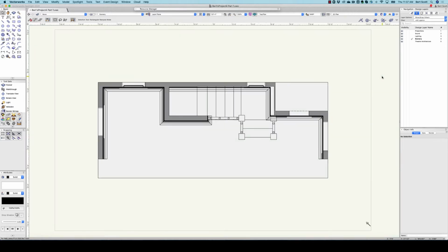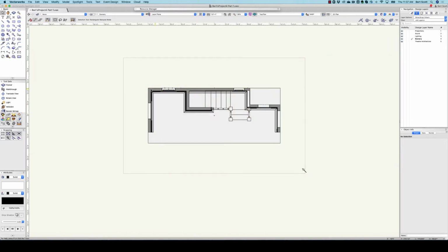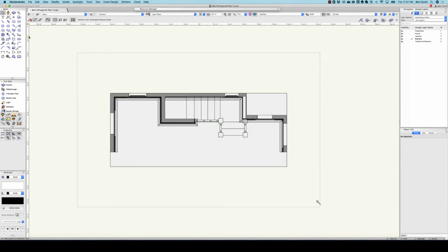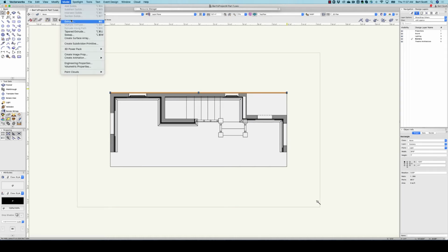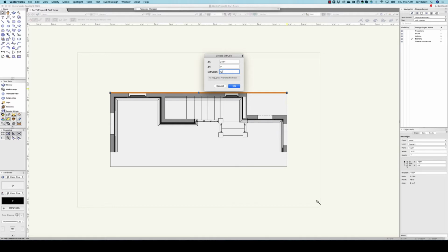And then the last part of our modeling is we want to create a backdrop in the back here. So I'm going to draw a rectangle that is the width of the set and is 1 inch high. This could represent a cloth backdrop. It could be a vinyl Translux backdrop. It could be flats. So it might not actually be 1 inch. It might be really thin if it's fabric or vinyl or something. But 1 inch is a good sort of stand-in. And then we're going to extrude that the height of the set, which is 12 feet 6.